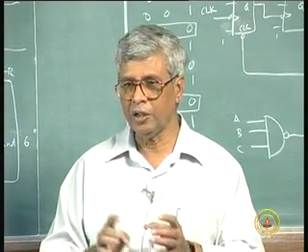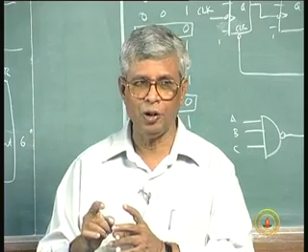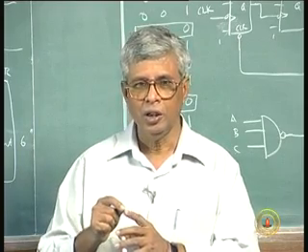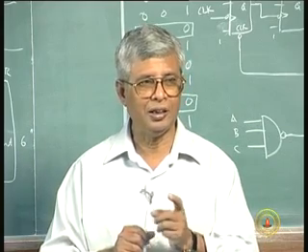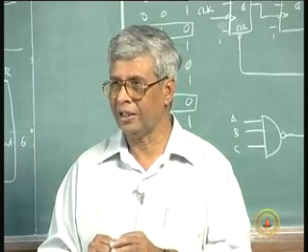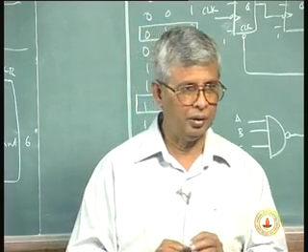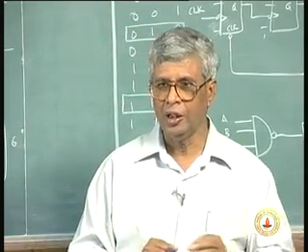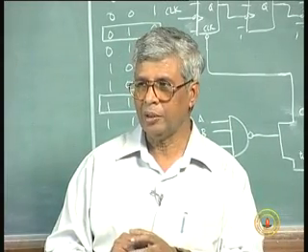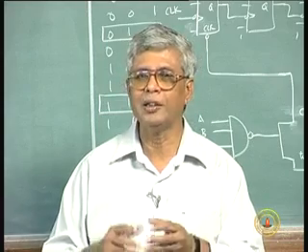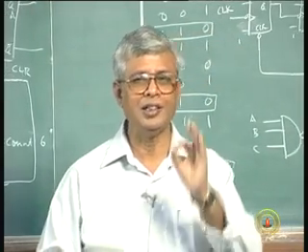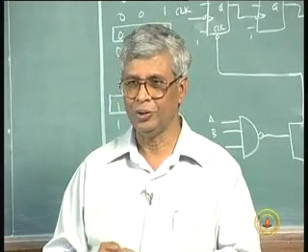So I am not giving you a clock of exact frequency, because I want a whole number finally. You can do a multiple of the clock, because 60 times 60, 3600 seconds make an hour, right? 60 minutes make an hour, 60 seconds make a minute. So 3600 seconds make an hour. So let us say, make it 3.6 megahertz. I am giving you a 3.6 megahertz clock.